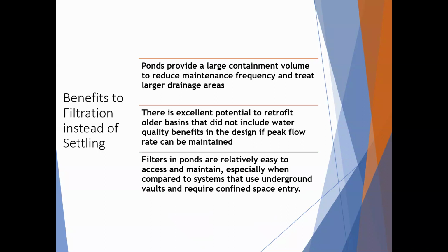Then also, filters in ponds are relatively easy to access and maintain, depending on how you put them in and what the system is. But if you compare that to an underground vault that requires confined space entry or some kind of specialty equipment, if we can incorporate a filter into a pond, we can get to it, right? So it's a little easier and doesn't require specialized equipment.